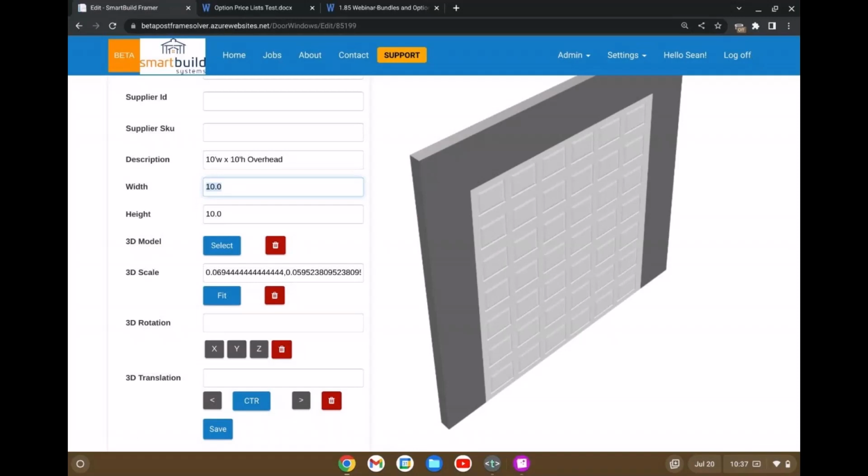And then again, I think there's a different problem with sliders. There's a different problem with windows and walk doors. For windows and walk doors, generally you will have a positive margin, if you will. Generally, the rough opening is wider than the door for a window or a walk door. For an overhead door, the rough opening is generally smaller than the door. So as it is now, the sliding door does have a side margin, and that does not change the framing. It changes the size of the panel.